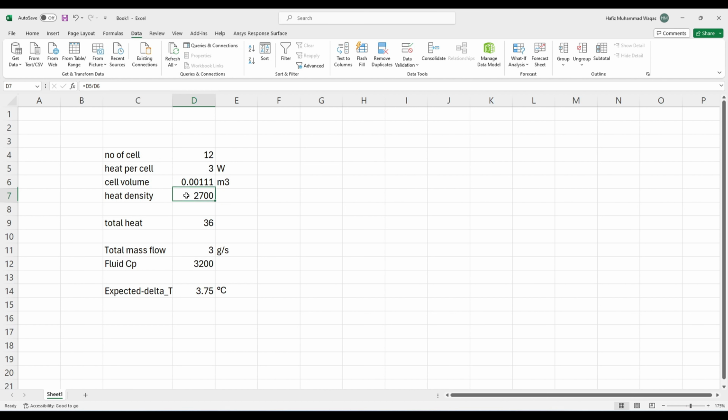Heat density, this value you have seen I had provided in the cell zone condition, which was watt per meter cube. In Fluent, heat is always provided into the watt per meter cube, or you can say heat density. So you get heat density by dividing these two values, this and this. This one is the total heat generation in this system, which is 3612 into 3.